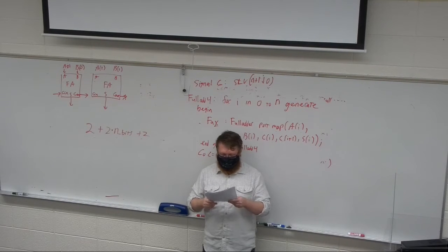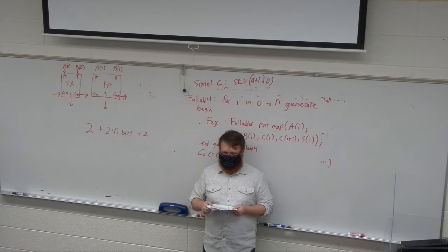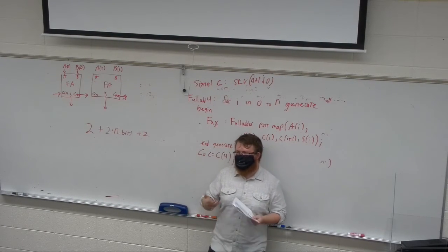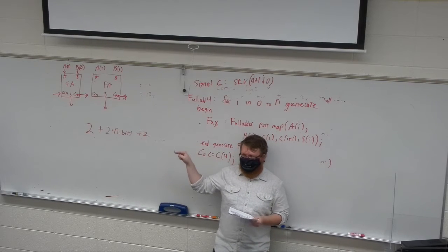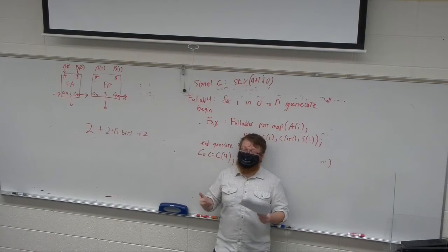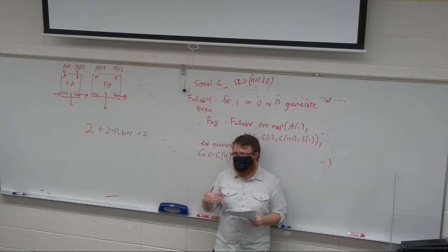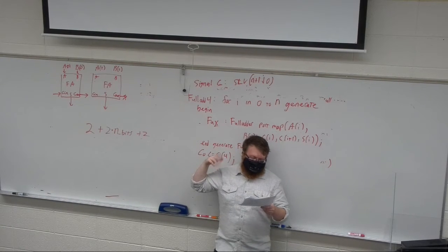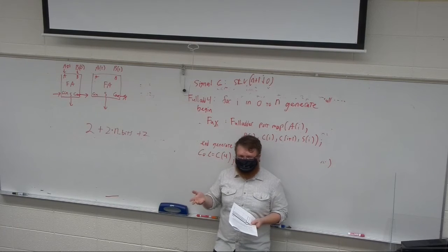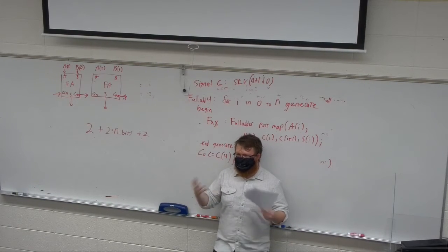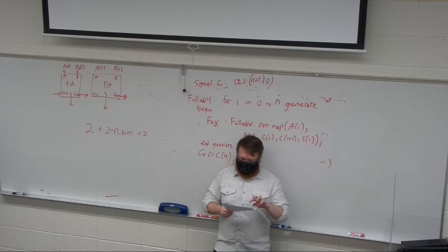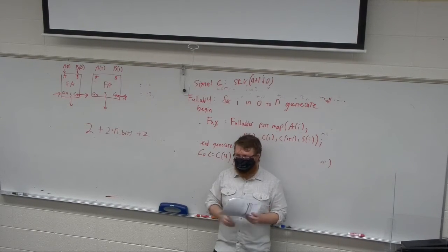Number 12, the main issue was chip select never goes high. Now, load could be viewed as a problem if you wrote the code as if rising edge upload. In general, you shouldn't do that, so you have partial credit for this. You shouldn't use rising edges on non-clock signals. So if load is still 1, it'll just keep going again. The busy is an output, so we don't really care about what busy is doing. The busy can simulate correctly, but it won't cause any issues in the system. Again, partial credit if that's what you did, but chip select is that it will fail because of that.